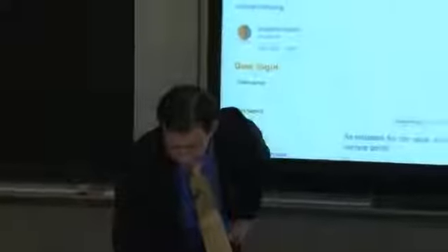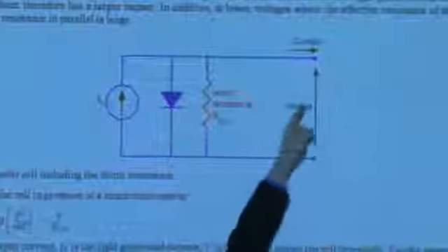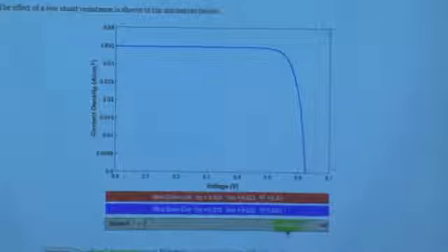In a shunt resistance, let me show you that as well. So we have another beautiful example of shunt resistance here. Now we start out with a very high shunt resistance because in our equivalent circuit diagram, if we go back up here, we have a large barrier that prevents the current from flowing back internally, inside of the device. The current is forced to go outside through the external circuit. But as we drop that red shunt resistance component right there, as we decrease the magnitude of the shunt resistance, we will allow the current to flow inside of the device.